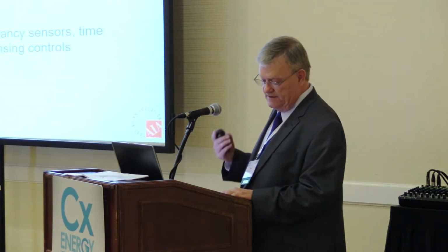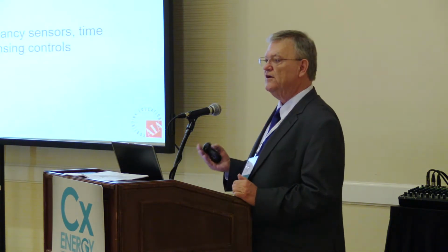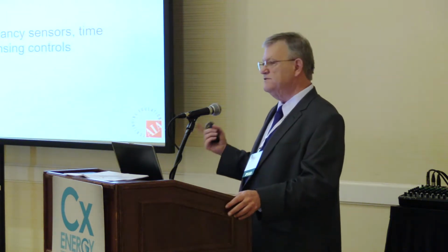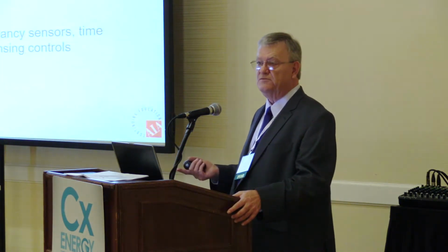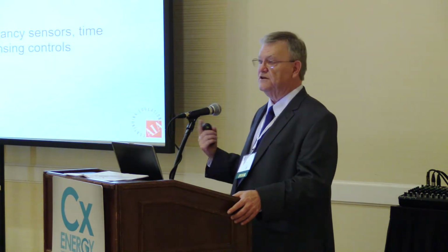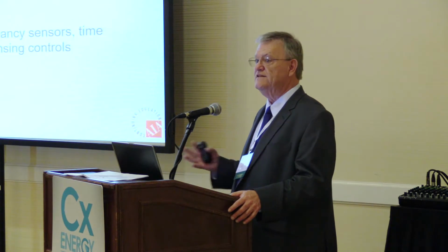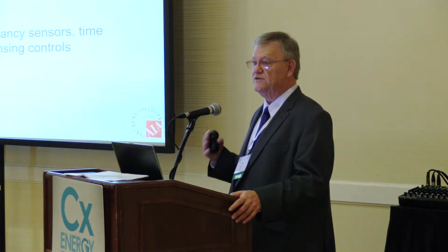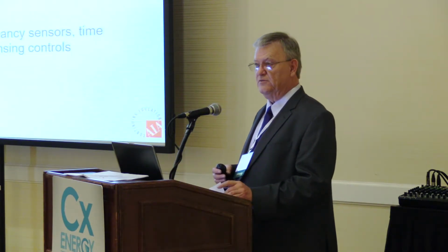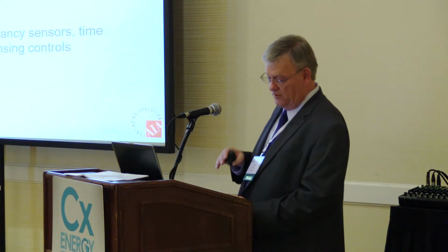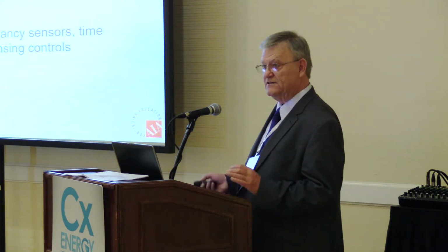The last one I see is verify the calibration, that calibration adjustments are accessible only to authorized personnel, which harkens to what Jesse said before about asking, have you seen occupants or building management disable some of these sensors and controls? Reading between the lines, what I see is that occupants aren't crazy about some of the lighting controls that they live with. They'll often try to adjust them or disable them if they can actually get to them. So ASHRAE 2013 requires that only authorized guys get a shot at that stuff.